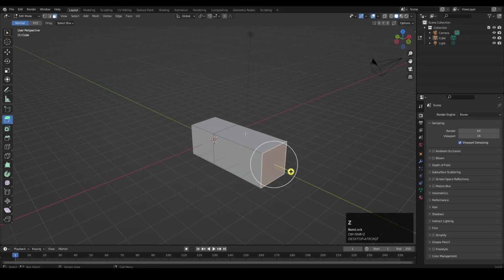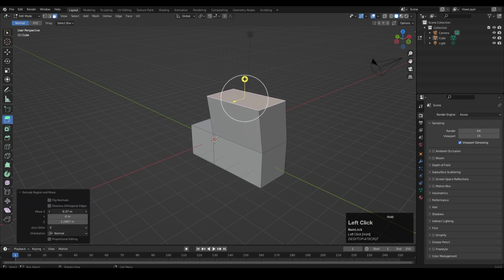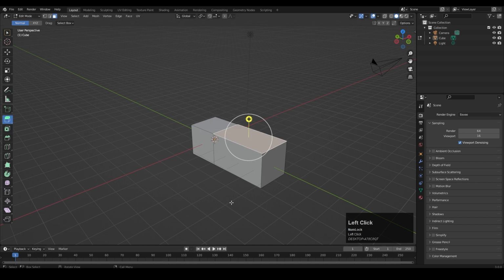The Extrude tool allows you to extrude an object in any direction. Select the face, pick the Extrude tool, and drag the gizmo. Or set values in the bottom box before deselecting.